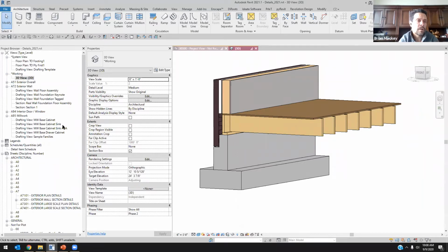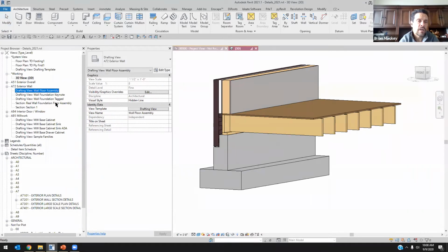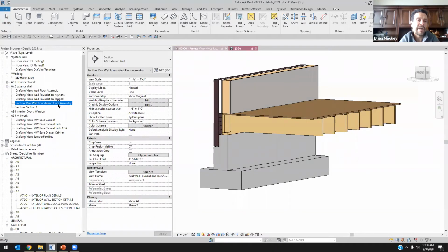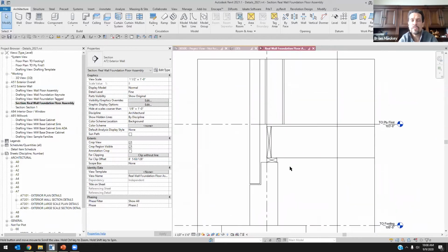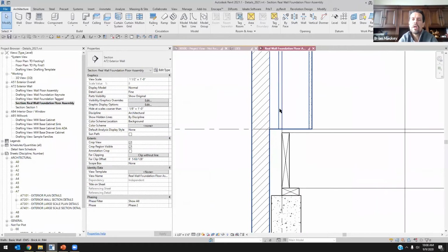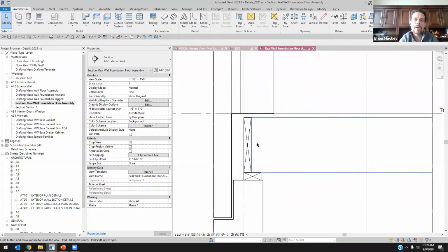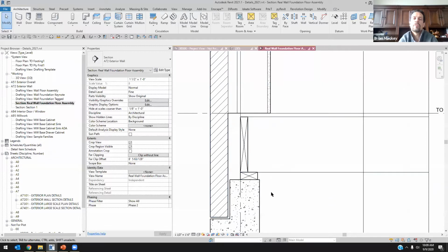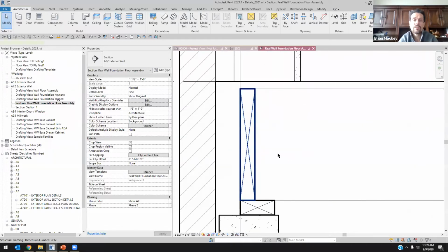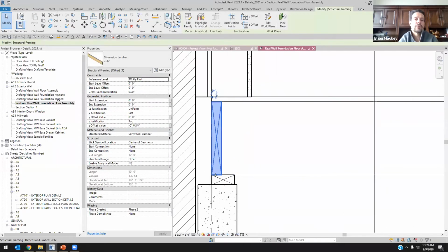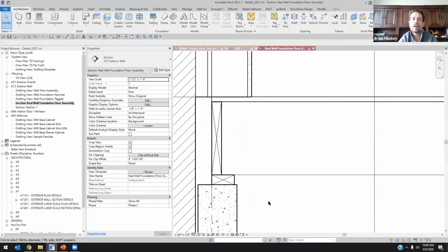So with that said, I'm going to jump into one of the views inside of Revit that we'll be looking at, right? I can come into the section of this live model, and you can start to see that yes, even though this is that section of the live model, I might need to now start showing the sheathing coming down a little bit farther. I might want to be able to do a little bit more than what we see inside of here, and even customize some of my families so that my dimensional lumber might have the X in it automatically. Out of the box, the 3D families don't.